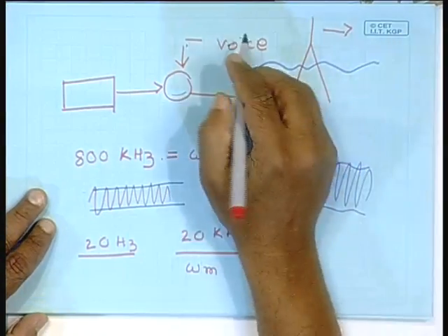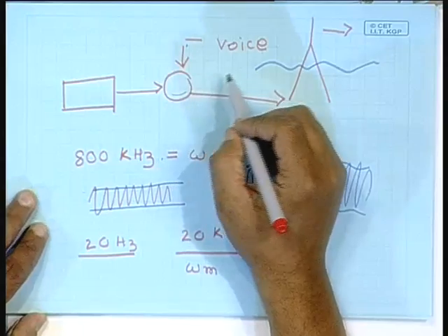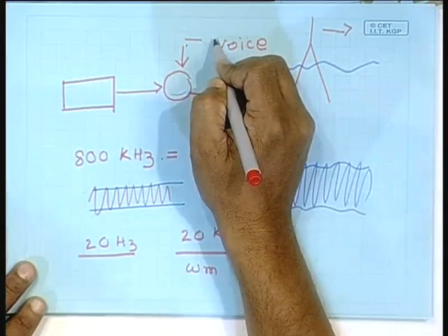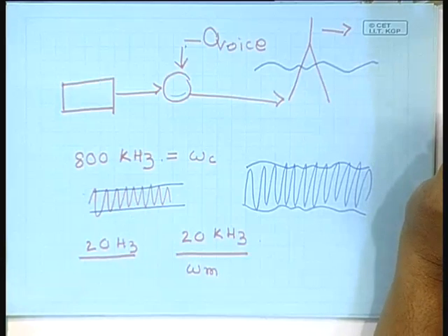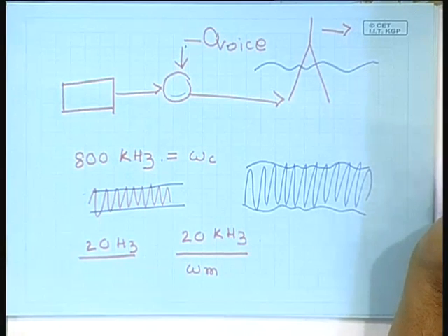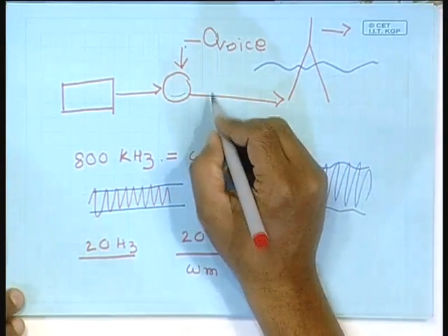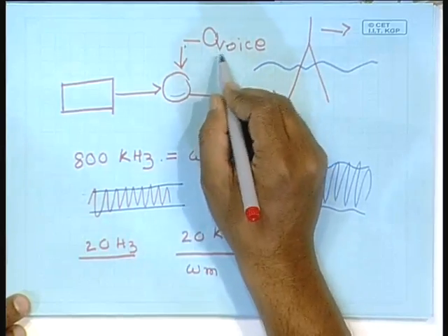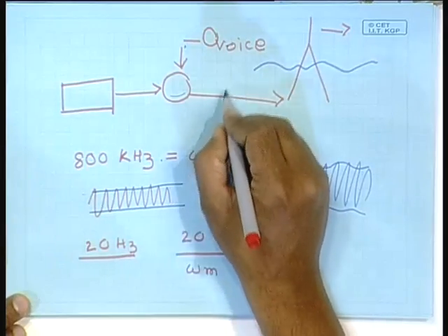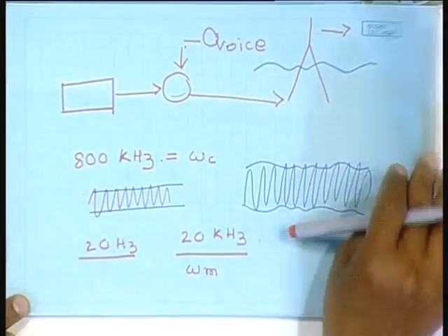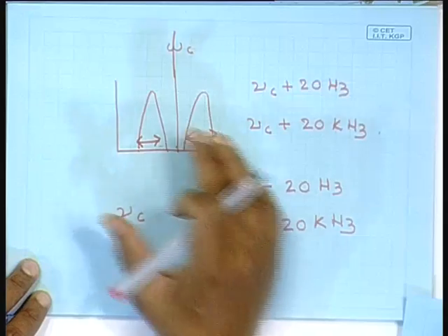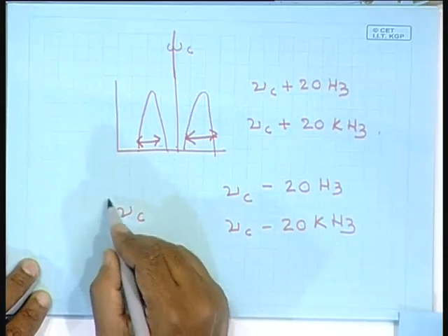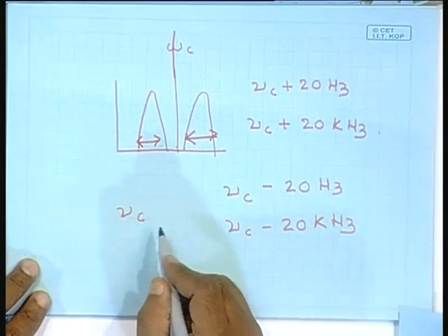Typically, the high frequency parts are not recorded, they are not very crucial unless you really want to have a high fidelity transmission, and typically the bandwidth the voice is recorded over is 10 kilohertz, not 20. So, typically each transmitter will span nu c, the carrier frequency, plus minus 10 kilohertz.